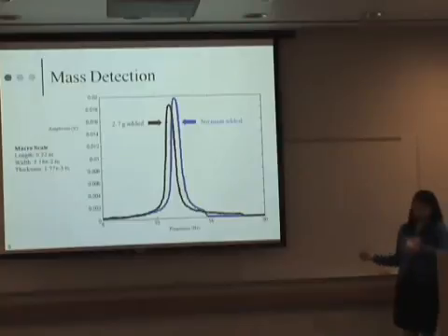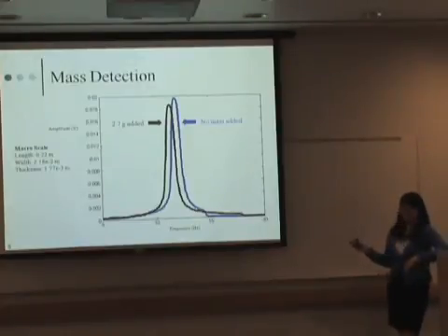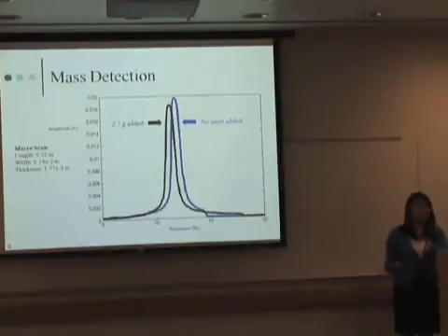With some initial experimentation, we discovered, or proved, that as mass is added to the cantilever, the frequency at which it oscillates decreases. So this can be used as mass detection. When you notice a change in frequency, you know that there's a change in mass of the cantilever.